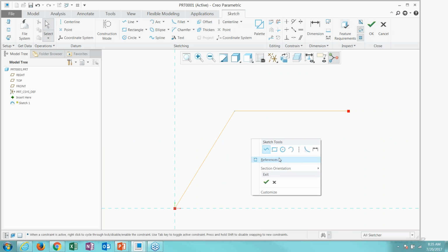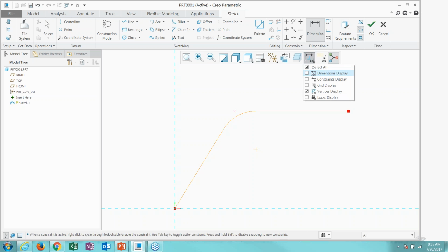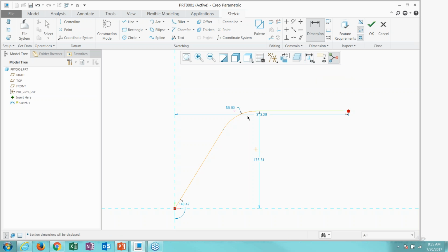I'm just drawing the trajectory of a sweep, and this would be a classic case where you might want to draw the fillet in there, because in reality you might also want to draw the point where for your dimensioning purposes you might want to add those dimensions, right, for manufacturing. They would obviously want to know from the theoretical sharp, that dimension. You might want to know this dimension here, as well as a bend radius, right, as you can see there.